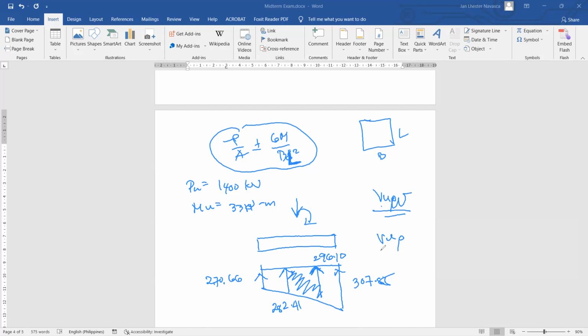And lastly, the maximum design moment. It is the same pressure diagram; the only question is the actual moment it causes at the face of our column, since the critical section for moment is at the face of the column. So this is the face of the column.